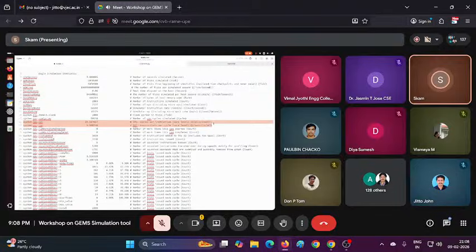In terms of IPC, how will you say that the policy is good? Only if the IPC is a higher value, meaning the number of instructions you can execute per cycle is good, then whatever you are proposing is good. But if it is reducing IPC, that means it is not a good method. This is how you will analyze your architecture or your implementation.